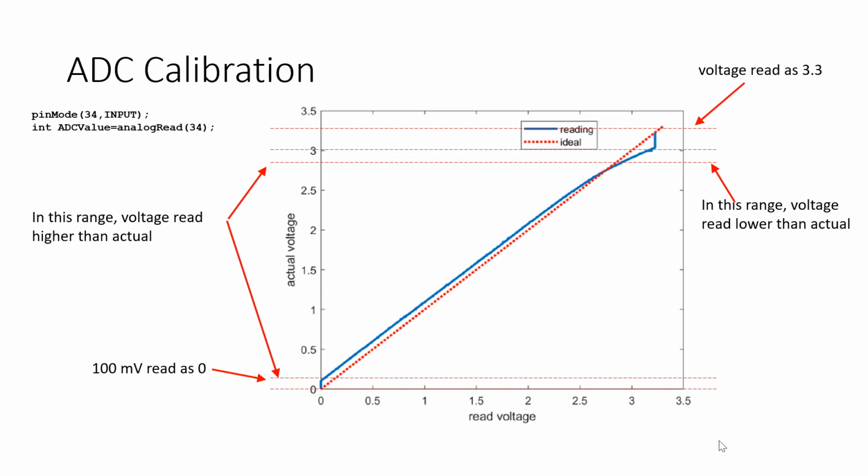Okay, so we compromised here, and in the lab sheet it says 50 millivolts. But that should be something you can change in your code pretty easy, right? Make sense? So I would just have that as a variable. So you're going to walk the power supply through the whole range in 50 millivolt increments, which will give you about 300 measurement points.